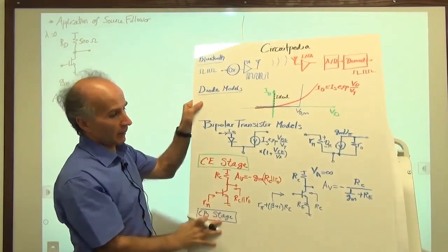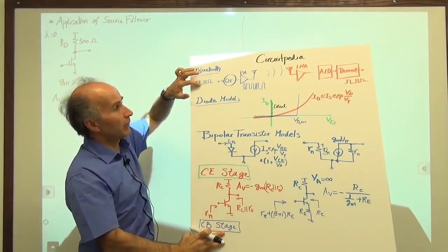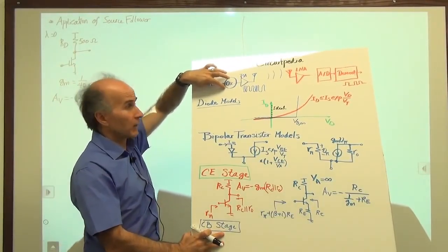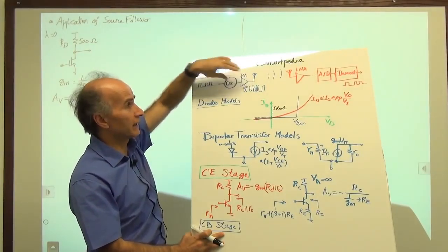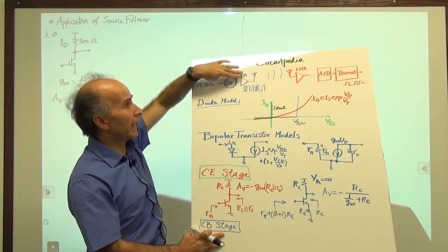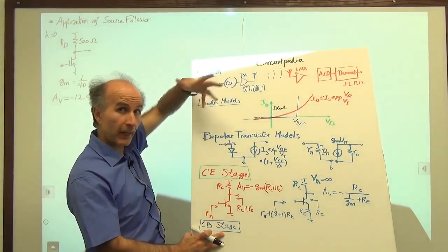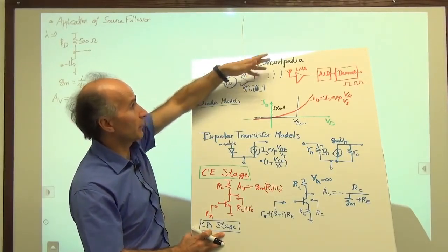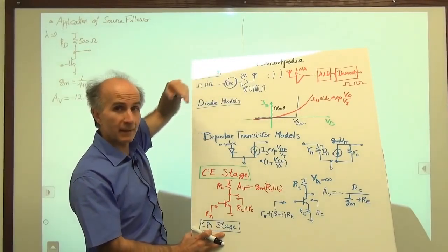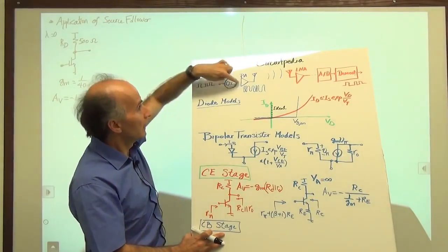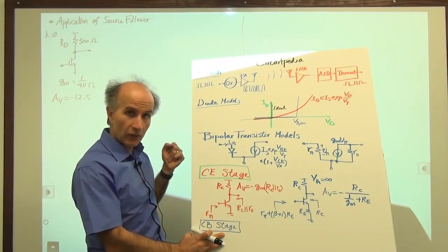So here's what we had, if you remember. We said that we apply our pulses to an oscillator so as to modulate its frequency. And then this output needs to drive an antenna. We need a power amplifier between the oscillator and the antenna so that it can deliver a high power to the antenna. We want to have a high power transmission so that the range between the transmitter and the receiver, the distance, is maximized. Okay, so this power amplifier, in its simplest case, might be just a common source stage.